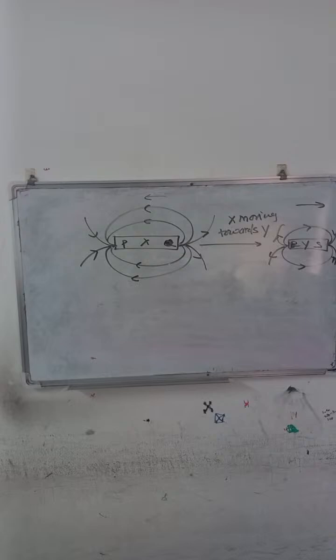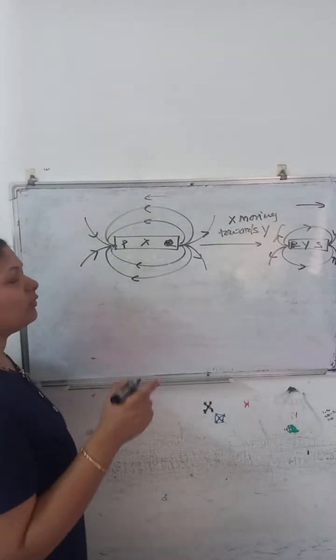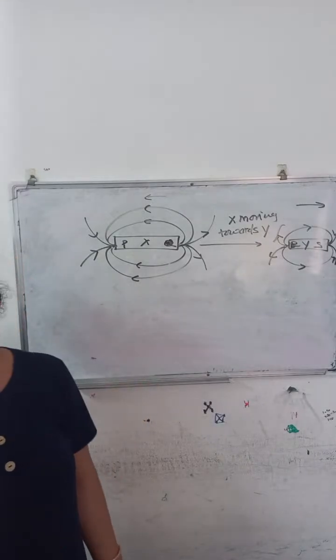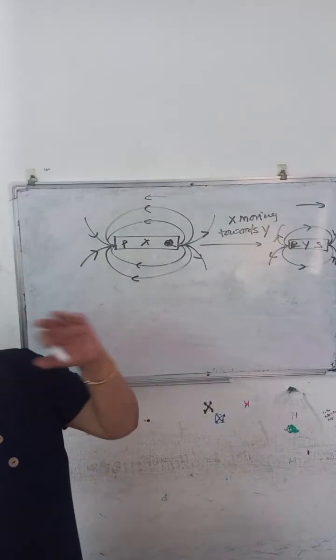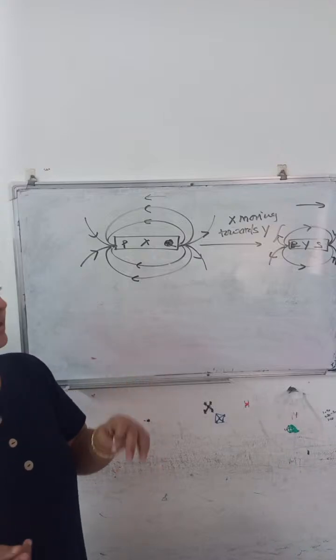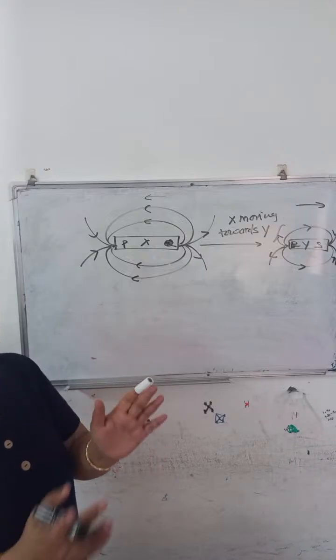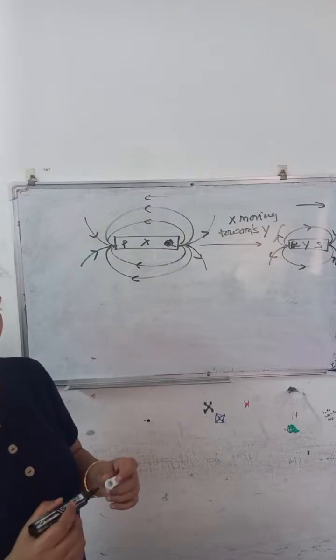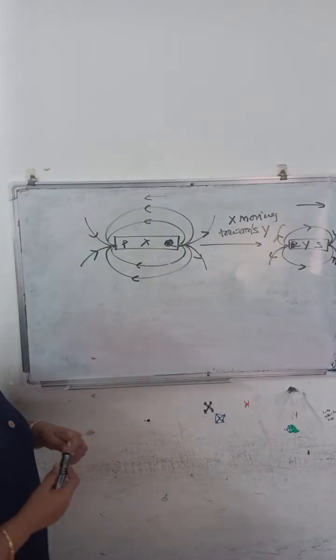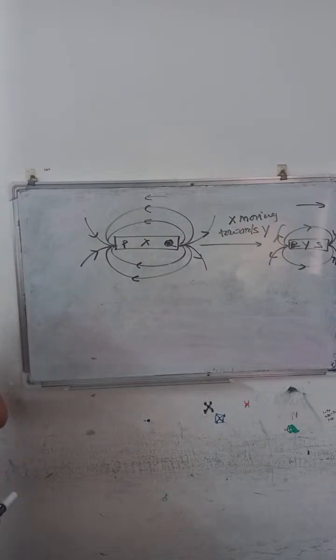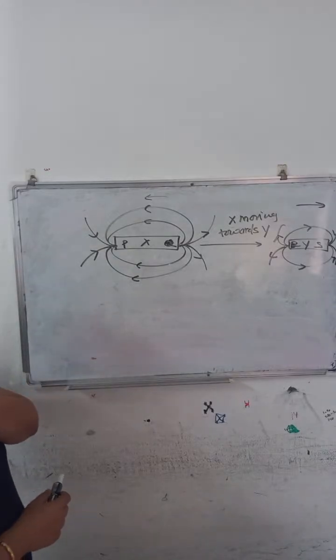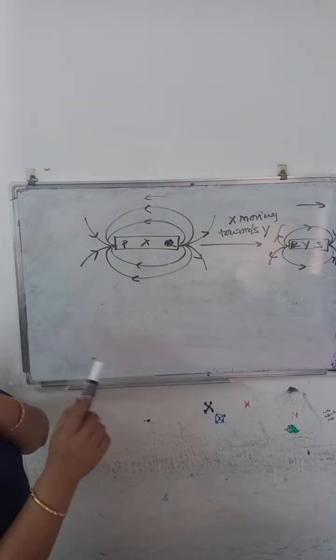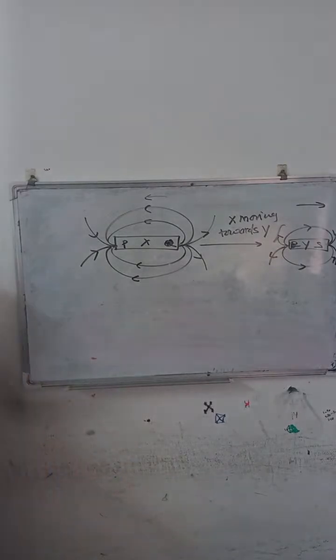Here the electrical fuse is connected in series, as the fuse has a very low melting point. Suppose an excess amount of current is flowing through the circuit, then it starts melting, and once it completely melts, it disconnects the supply. That means there is a short circuit. This is the use of a fuse. Basically, to avoid excess current and damage to the appliances, we use a fuse.